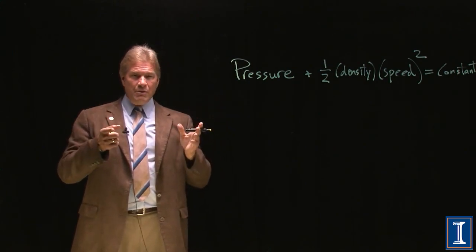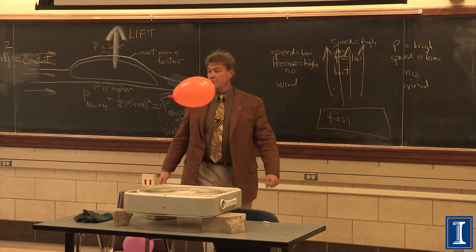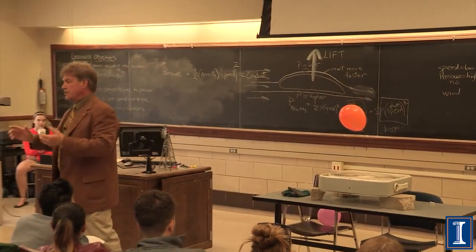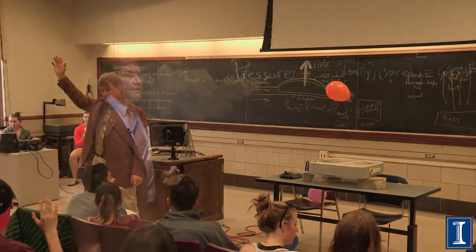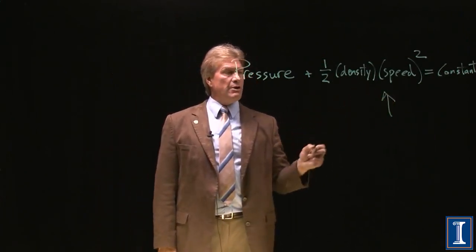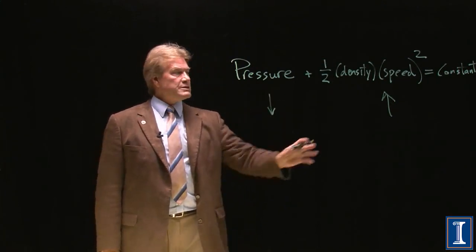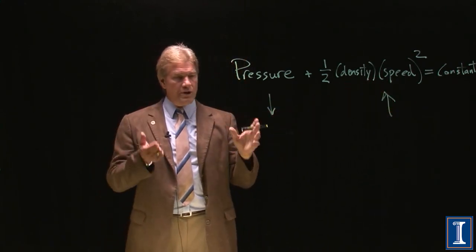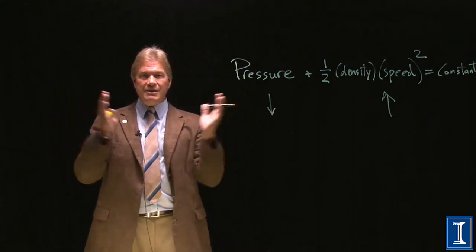We've got a great demo of fans. The balloon actually sucks into where the wind is blowing. That's hard to believe. Usually you think, oh, the wind is blowing, this is where the pressure is going to be higher. But if we think about the Bernoulli principle equation, if the speed of the wind is high, because the fan's blowing, for this to be the same, the pressure is going to have to be lower. And outside where this wind is small, where there's no speed of the fluid, then the pressure is actually larger. So a balloon actually is sucked into where the wind is blowing.